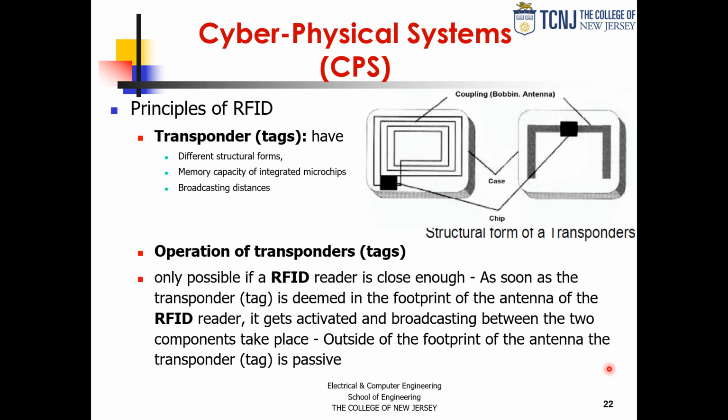So if you look at the physical architecture of these things, you would see that they have the chip, and then they have some type of coil-like antenna that lends itself to energy harvesting, because with a coil you get some inductive-like coupling through a magnetic field, or to the magnetic field part of the electromagnetic radio wave that you are receiving.